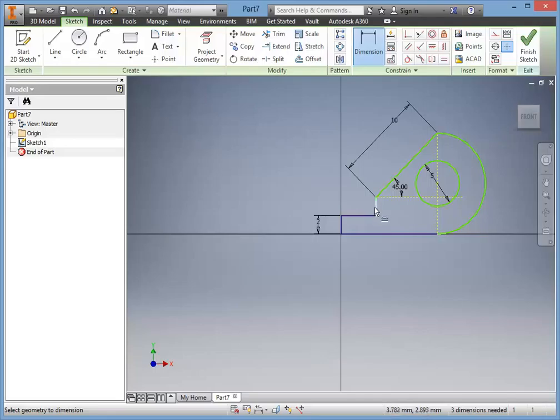Let's say that I want to measure this line, so I do the same thing. I click on that line, drag it out. It's already 2 millimeters, and that's what I'd like, so I press the green check mark. This line right here, I would like to measure the distance between this line, so I'm going to click on it, and this line, and click on it. When I pull down, the program automatically draws lines to measure the distance between those two lines.